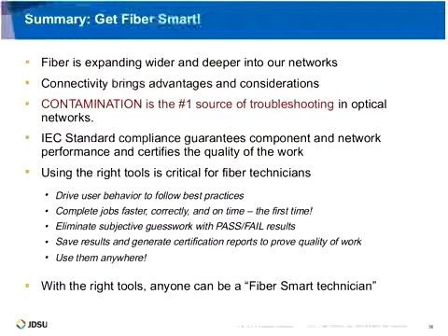But my recommendation is, no matter what, you always need to inspect the connector of the patch cord after you receive it, because it could have left that facility perfectly clean, but like the example I gave, it could go through all sorts of environmental or temperature changes from the time it left the facility to the time it reaches the end user's hands.